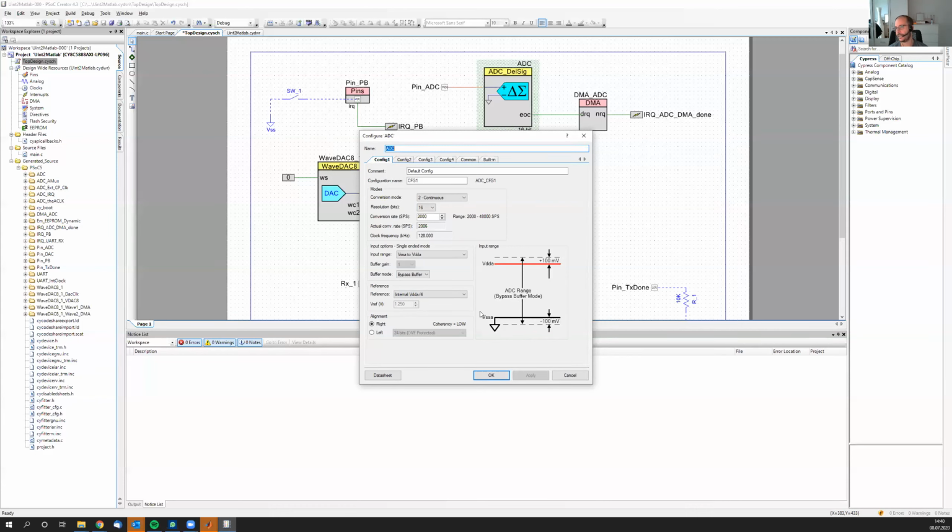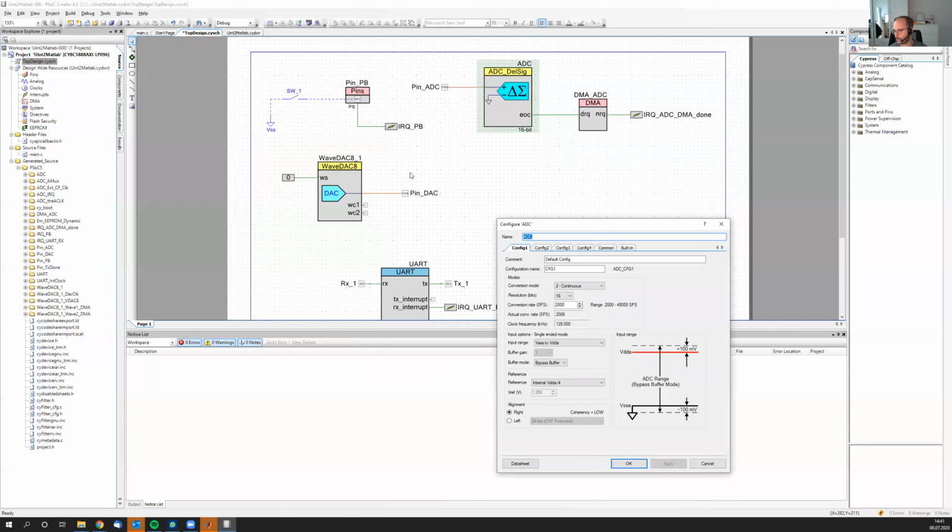Which has a little bit the advantage if you know that, for example, you connect them, you make one test run, okay? You connect those two together without the amplifier circuit, and then you can kind of calibrate that stuff, yeah? Because then you read out the signal, you know what you're expecting, and then you can adjust this multiplication factor in such a way that it also shows your expected values, okay? If this is just 1-to-1. And then you can bring in your bandpass circuitry, and then you know that this is approximately the right configuration for that.